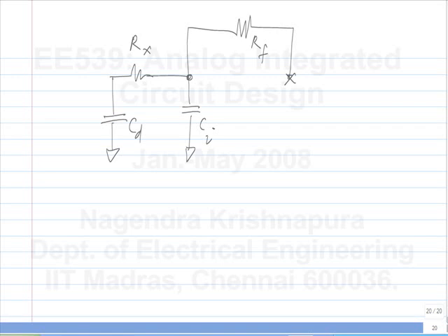What is the phase shift in the feedback? Minus 90 degrees. Okay. When Rx is very large, what happens? So you can ignore this part and it will still be a low pass filter. So in general, this tends to give you a lot more phase shift than the other circuits we saw.